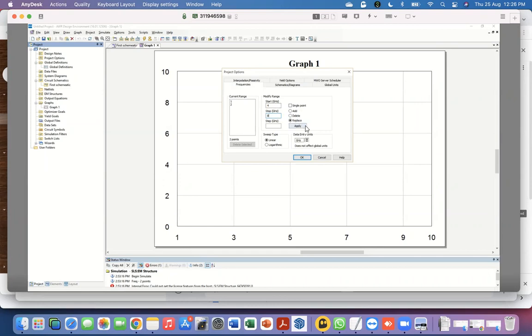Most of the time, it creates problems. And the biggest mistake, which at least I remember many I have done and many of the people have shown done, is that after you do this, you have to click apply before you hit OK. Unless that number comes here, it will not simulate. And this can be something which you miss out. So let's say 4 to 8 gigahertz and 0.1 gigahertz step size. Then you hit apply. So then this list gets populated from 4 all the way to 8 at 0.1 gigahertz spacing, and gives you the total number of points here, right?